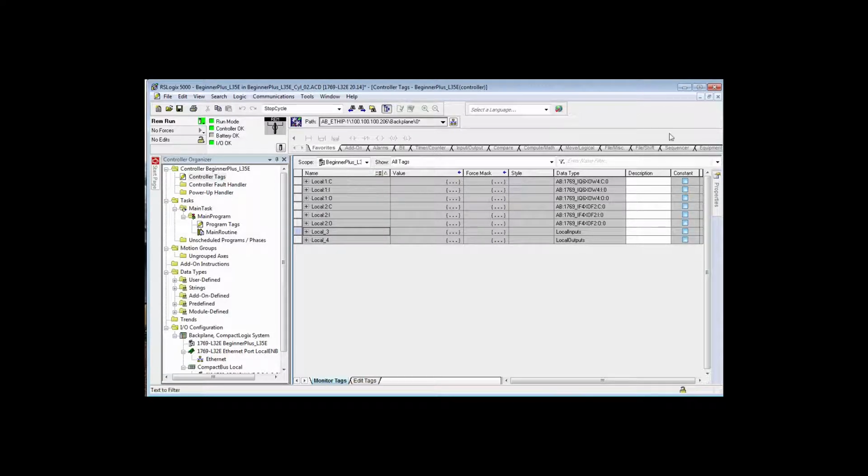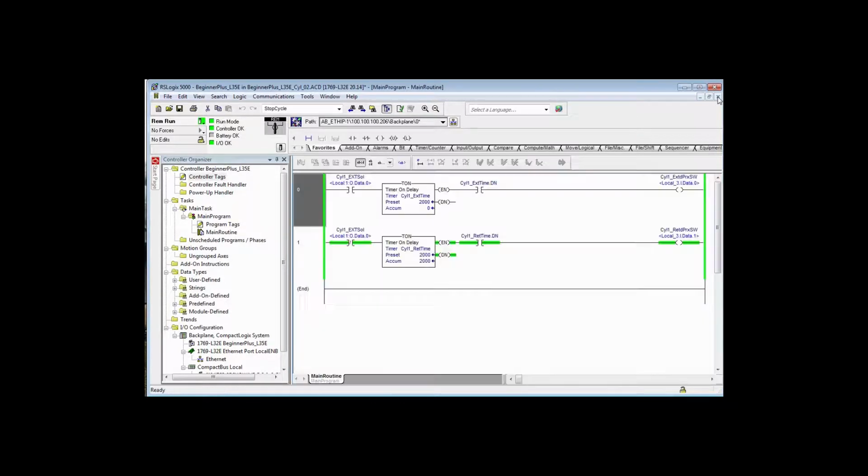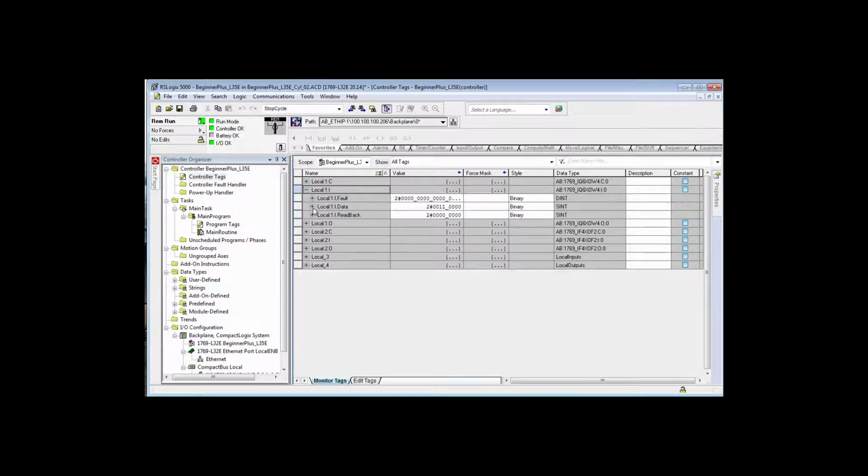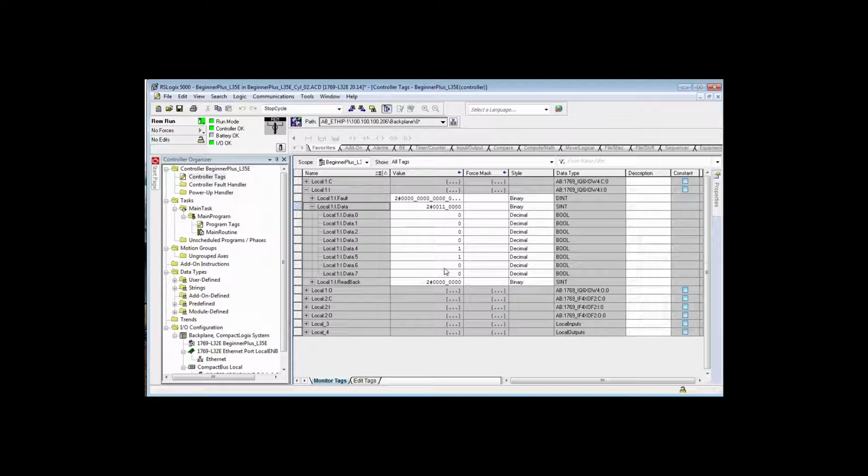So we're actually turning on a bit that would simulate an input. Now you can't turn on an input in a real program where you actually have input modules. And this goes way back to the beginning in the first manual, where if you have, we'll just do it right here, data. Okay, you see that 4 and 5 are on there, right?